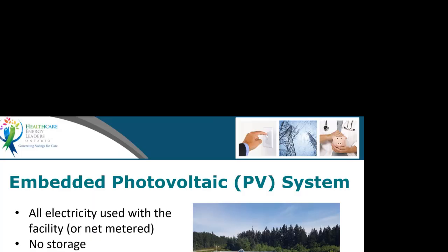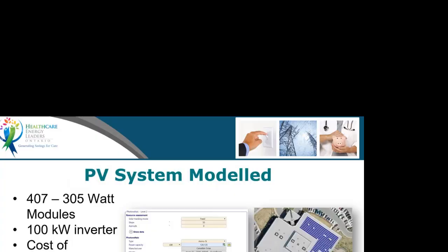The picture I have here is a healthcare facility, West Coast General Hospital out west, where a fairly good size array of panels was placed. I think that's an aerial view, it might have been Google Earth, I pulled that off. It's basically another view of the hospital. 407 305-watt modules, 100 kilowatt inverter. The cost of their system was $2.58 a watt, or about $2,500 a kilowatt, and I would say prices are sitting there.